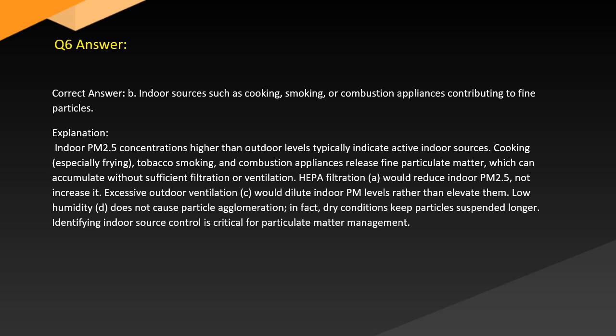HEPA filtration, A, would reduce indoor PM2.5, not increase it. Excessive outdoor ventilation, C, would dilute indoor PM levels rather than elevate them. Low humidity, D, does not cause particle agglomeration. In fact, dry conditions keep particles suspended longer. Identifying indoor source control is critical for particulate matter management.